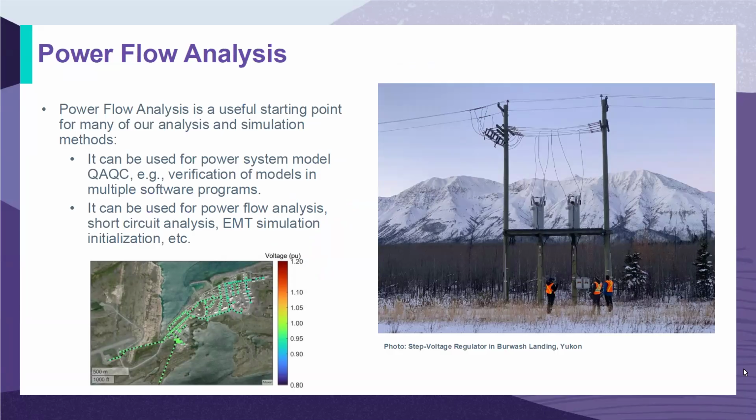So for our power flow analysis, we look at the extreme examples. We use MATLAB, particularly MATLAB Simulink in the Simscape Electrical power tools. We use Stateflow analysis to implement the microgrid controller, and we also use Simulink power systems for the electromagnetic transient analysis. The reason we use MATLAB is because we have a lot of flexibility in crafting our own models. So if there's an ability to implement a model we haven't seen, we could do so in MATLAB. It's like a Swiss Army knife. It can do almost anything, but it doesn't do anything particularly well. There isn't a customized solution that is best for it.